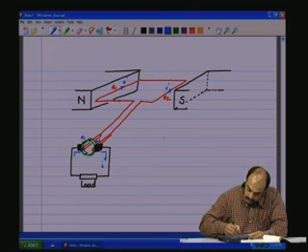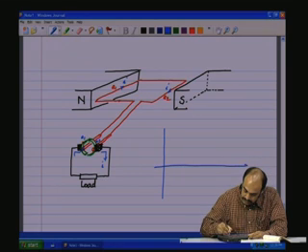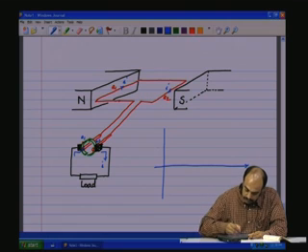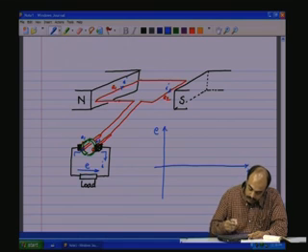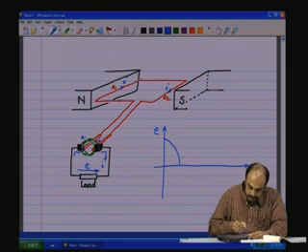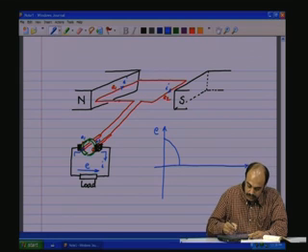So therefore, you would see on the time axis, time versus the induced EMF E here, it starts with a peak like that, and then the moment it comes to 0 here, when it is on the orthogonal plane, flux is 0.